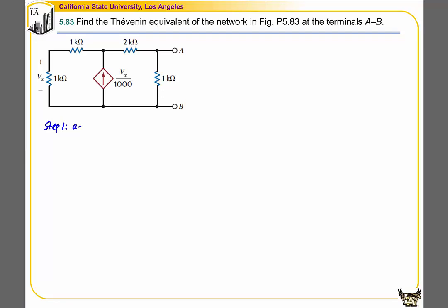So we're going to add a voltage source, a 1 volt voltage source. So this is 1 volt. Then we can calculate for the current that goes into the network. So this current is I. We can calculate resistance by using 1 volt divided by this current I. At the same time, we know that the open circuit voltage is equal to 0 volts.